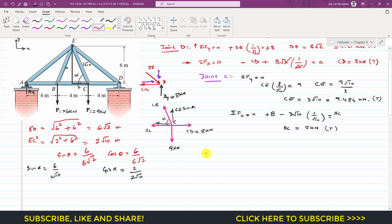So let me write that joint B. At joint B, we will have that BC force. So BC force is the tension force, so it will be acting away as well. So this is that BC force. Its magnitude is 5 kilonewton. And then we will have this AB member force. And then we will have this BE. So this BE is making that same angle alpha.